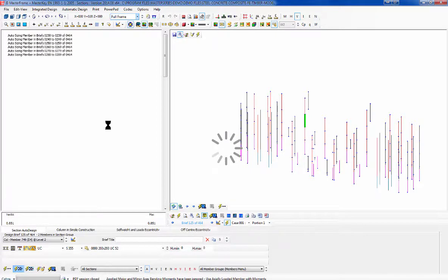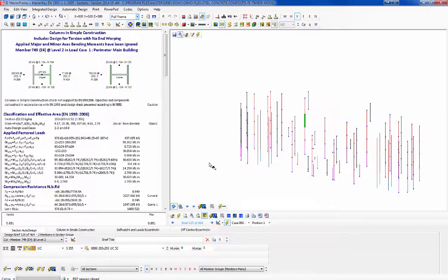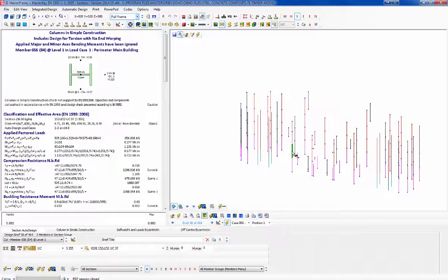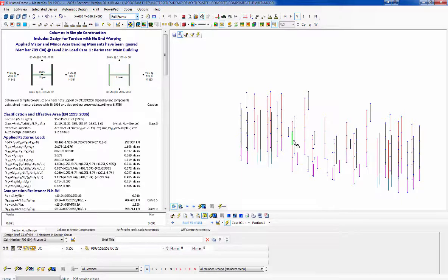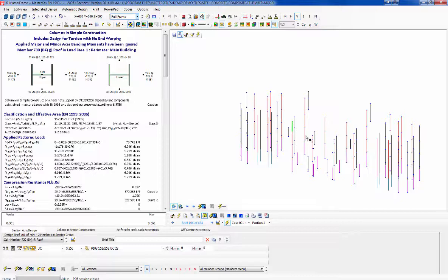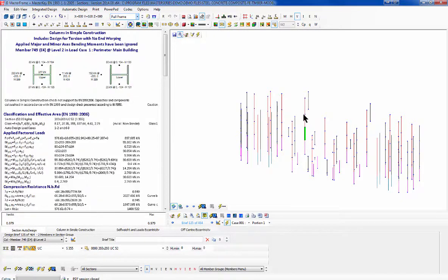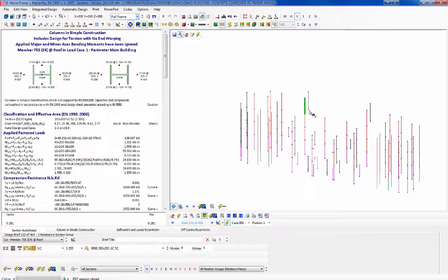So we're only going to splice below from here to here. Bear in mind this is a concrete column here. So this member is a 37 kilogram and that one's a 23, and this one also will be the 23. Likewise, as we saw here, 60, 52, 52. So it's again tying in and making rational decisions.